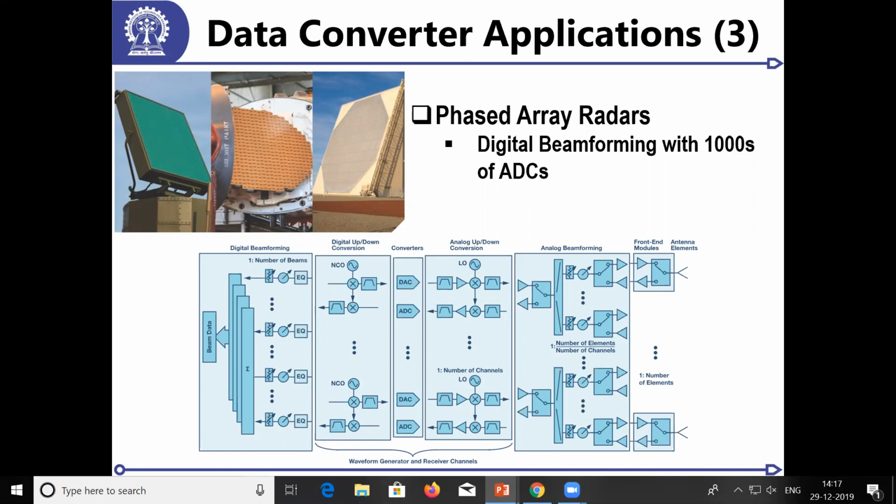And this is the overall architecture. I got this from Analog Devices application notes. So they'll have 3000 systems. I cannot get into the details of this, but you can see that there is an ADC and a DAC sitting over here. This is one of the latest applications where you have tons of ADCs and DACs used in a system, and they burn close to kilowatts of power, because each one would be burning close to 1 watt. 3000 is right there, 3 kilowatts of power in one system. So imagine the amount of cooling that is required to make sure that the system works. I think this is one of the systems that has that.